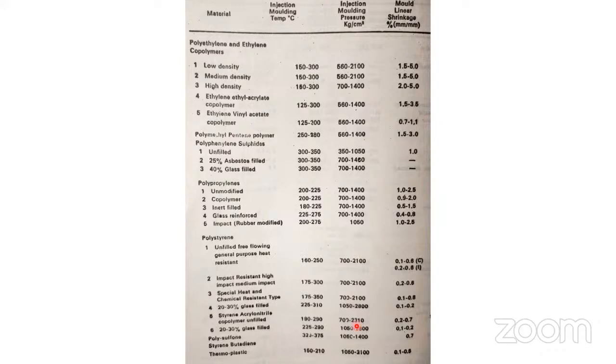Sorry to interrupt you. In between, you mentioned ABS plus GF, right? Generally we are using PP plus GF, but I have never seen ABS plus GF. So, for which property are we adding GF in ABS? ABS, if you see, dimensional stability property can be enhanced by adding glass fibers in the ABS, friend. And this is the only property we require: dimensional stability in terms of shrinkage, right?